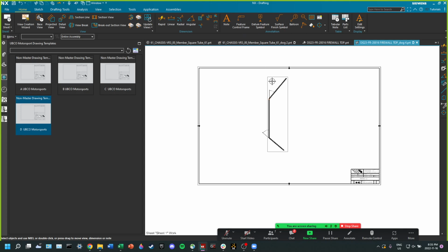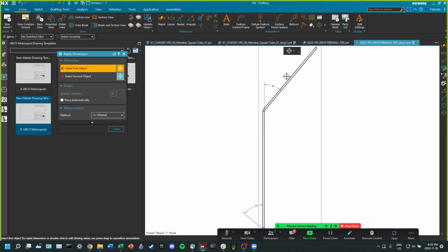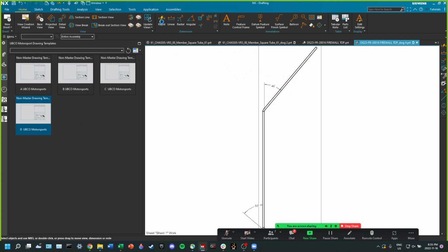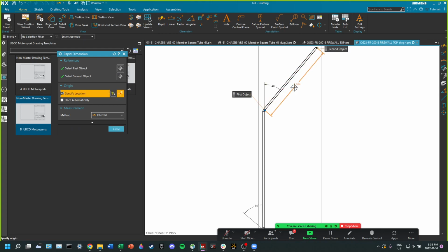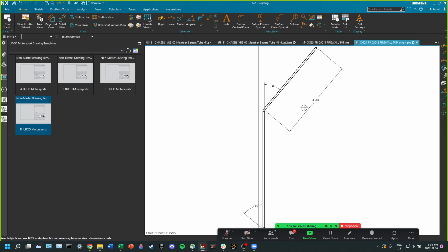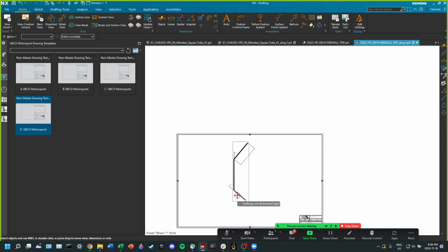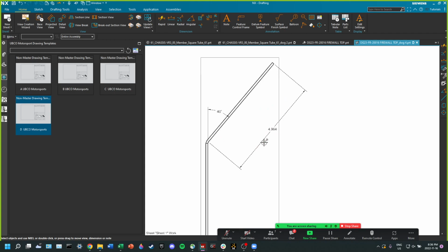Tolerance is specific to a certain point. Oh yes. So let's go with this. This is one of those times where it's like, okay, this is 4.96. I'm sure this is a sheet metal part, so ideally the drawing would be a flat pattern drawing, and then you do your dimension on it. But I'm sure this is supposed to be 5 inches.